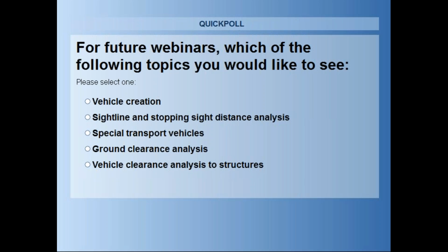What characteristics determine the different radii abilities at different speeds? Well, the turning characteristics of the vehicles are given by the steering angle and the wheelbase in most of the cases. In the case of special transport, you have rear steering axles, so the effective wheelbase changes as well. The way it works is AutoTURN will check vehicle turning characteristics up to a certain speed, and from there we'll use the actual equation to simulate the movement.